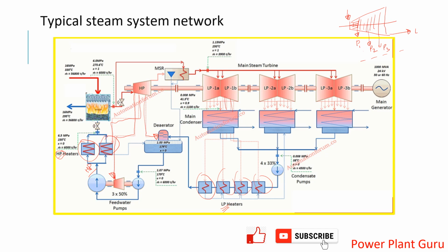For that purpose there will also be a supply to this deaerator from maybe a different auxiliary steam, or from another boiler system or auxiliary boiler system, so that it fulfills the startup steam requirement so that your boiler can start. And then once the boiler is up and running, they start rolling the turbine.